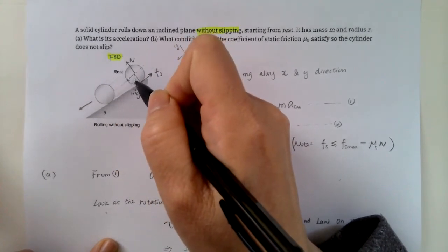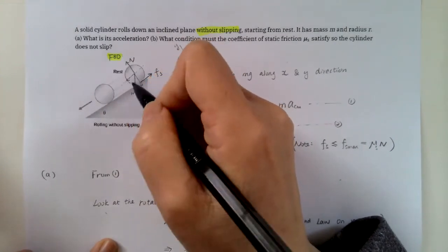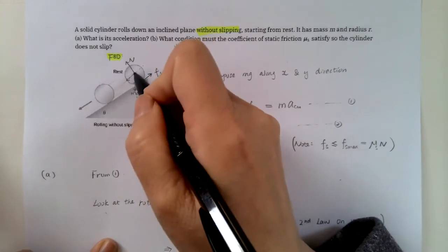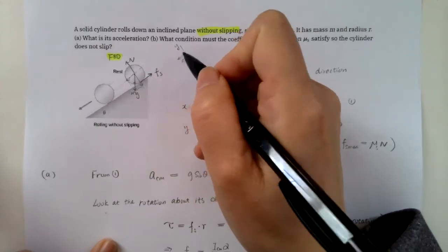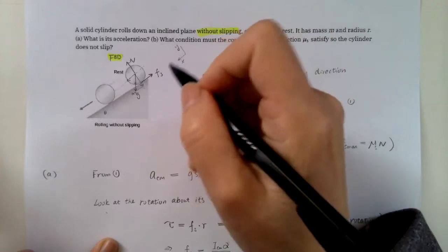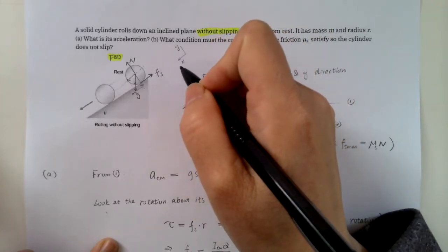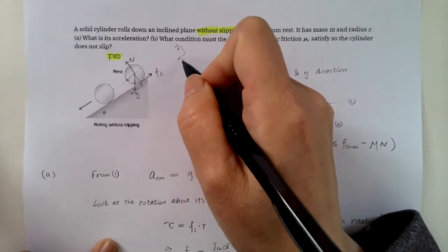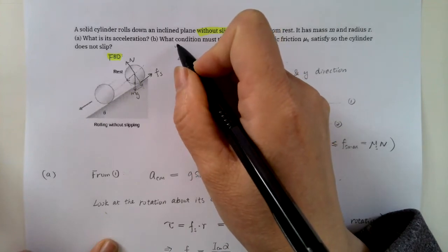Now, before we step on to write down the equations, let's decompose the gravity along x and y. So look at what I chose here. I picked an inclined two-dimensional Cartesian coordinate system, along the surface pointing down, that's the x positive direction, and the normal to the plane, I have as the positive y direction.